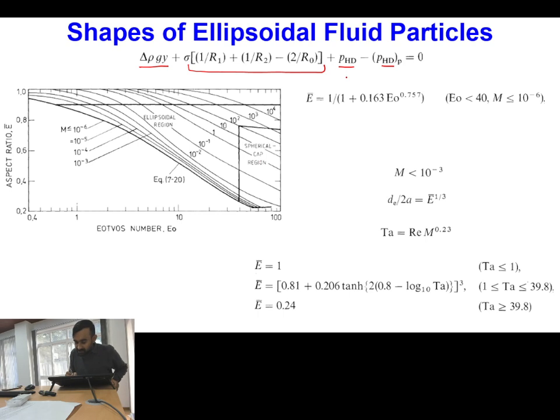So this is the additional pressure in the continuous liquid because of the fluid motion, and this is the additional pressure within the particle due to internal circulations present within the particle. Is this point clear? Once the particle has fluid motion, the fluid motion will also generate certain pressure, and that pressure we have to account for.